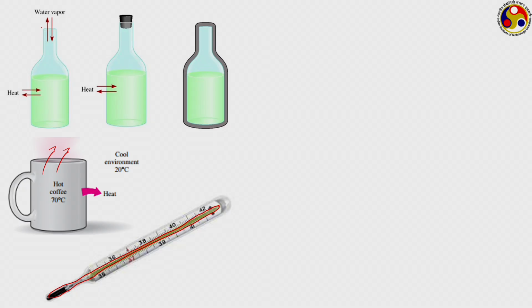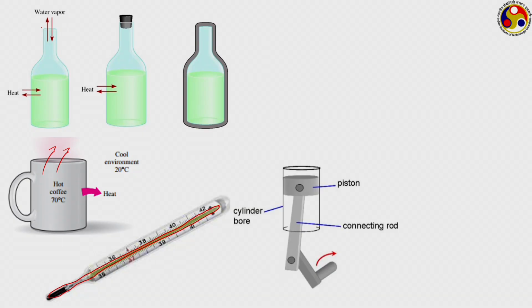Now, when you take this thermometer in contact with our body, there will be some kind of energy interaction. So, it is not an isolated system, energy interaction is taking place. Now, is there any mass interaction between system and surroundings? The boundary we have drawn is a rigid boundary, a real boundary. In this case, you do not have to imagine the boundary, because the capillary tube has a fixed wall. So, there is no mass interaction, the mercury or whatever thermometric fluid you are using is not allowed to come outside this capillary tube, and so it is an example of a closed system.